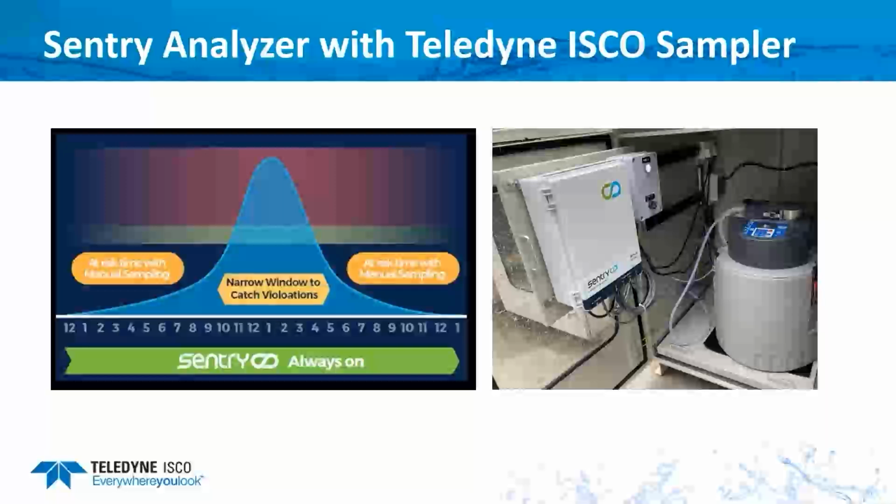If you have a toxicity event that only lasts 10 minutes and you're collecting samples every 15 minutes, chances are you may miss the entire event altogether, because you may collect a sample before the event begins to occur. The event happens, hits its peak, begins to fall, and is no longer in play when the next sample is collected, and therefore we have no visibility that we had such an event in our sample analysis.